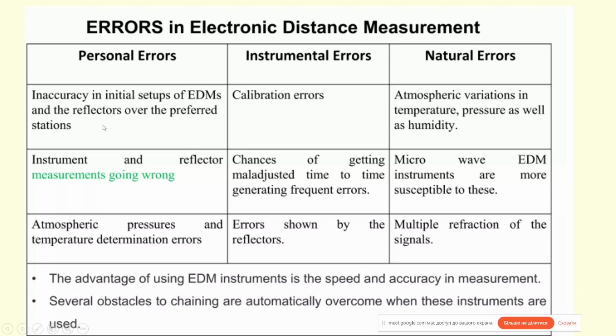Inaccuracy in initial setup of EDMs and reflectors over the preferred stations. Instrument and reflector measurements going wrong. Atmospheric pressure and temperature determination errors.